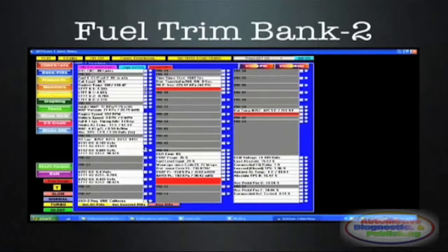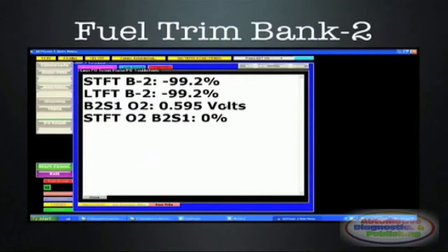On screen, we can see the same procedure being repeated, but for Bank 2. In today's VE-type engines, it is very common to see only half of the engine working properly. Be aware of the fact that a wide number of systems use cross-feed injectors, so the faulty issue could be located at the opposite faulty cylinder bank.